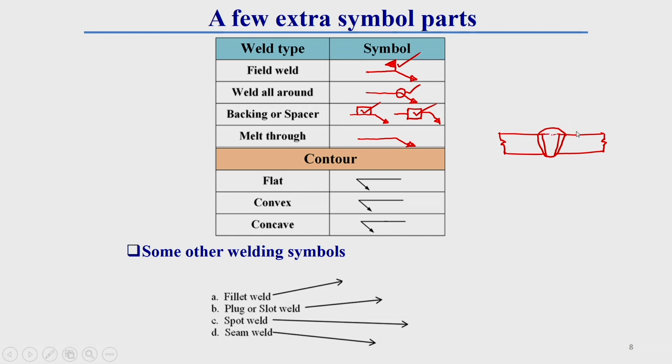Here each of the parts we should know. Here, in this portion on the bottom side, some extra molten material comes out. This portion is called melt through. This is sometimes required, and there is some specific range of this melt through height. This is generally required for the strength requirement of a welded joint. So, this melt through is also sometimes called bottom reinforcement.